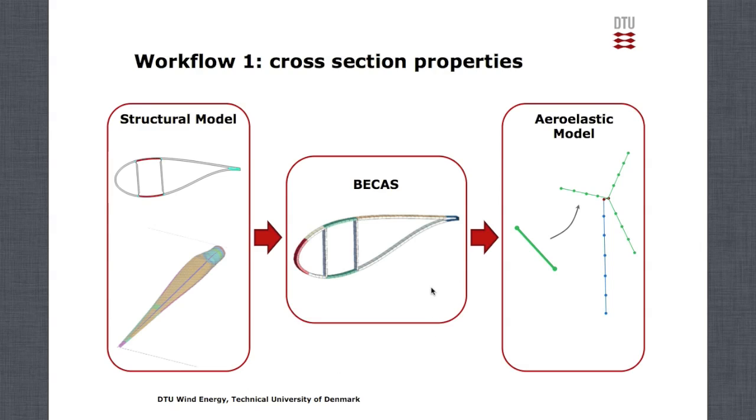You're going to define a 2D finite element mesh of that cross section, where the material properties are defined at each element, and the geometry is defined by the finite element mesh. Using that you will determine the cross-section stiffness and mass properties, which are used to generate the beam finite element model, which is then fitted into the beam assembly here, representing the blades in your aeroelastic analysis model.